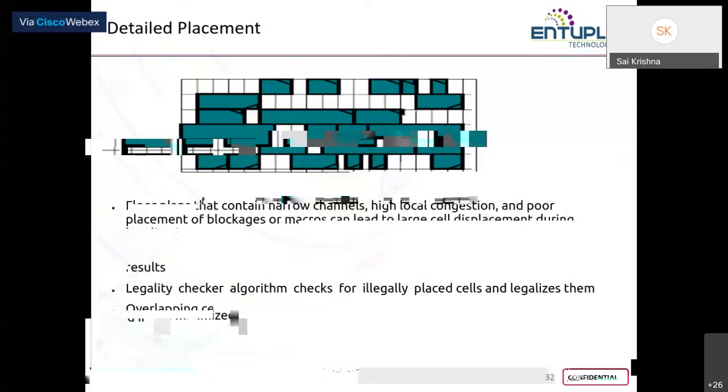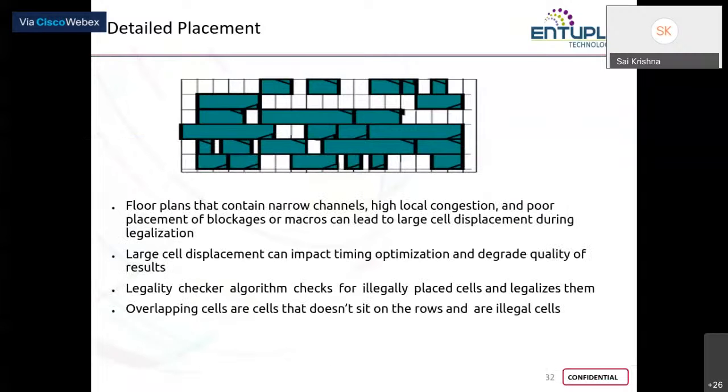Okay. So there are four things that you have to check after your placement is done. The first one you have to check is congestion. As I said, normally there will be certain space between two adjacent cells whose opposite faces contain pins, but sometimes your EDA tool might miss it.